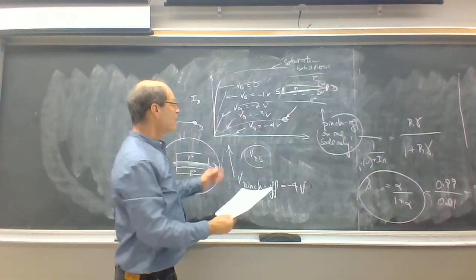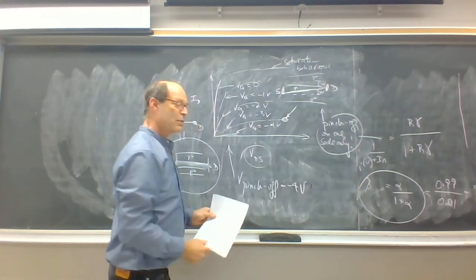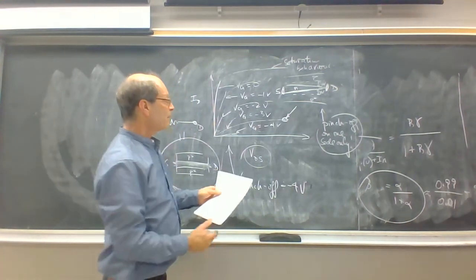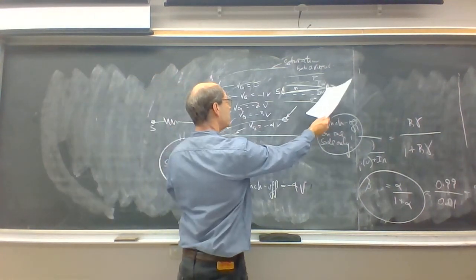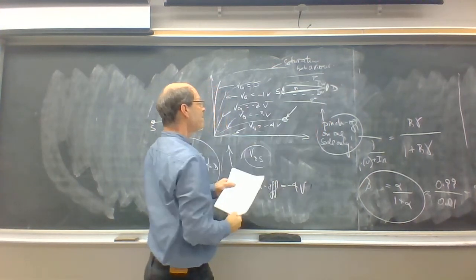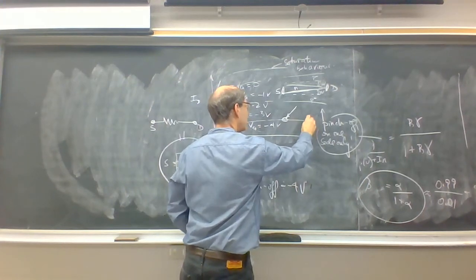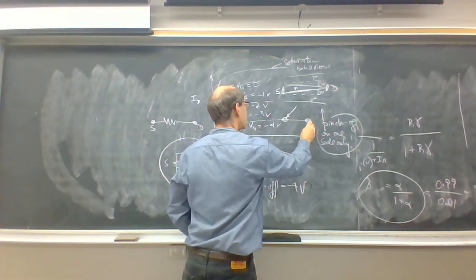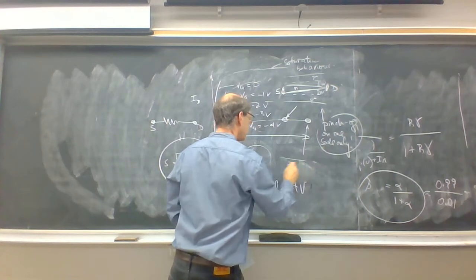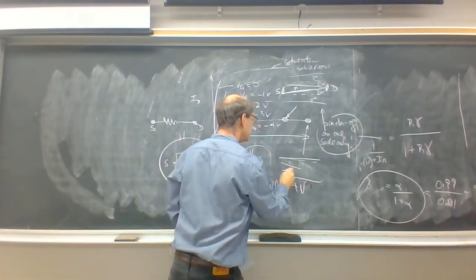What happens is you can change the voltage across the drain and the source, and you'll move the pinch-off point inwards towards the source. So if I go to a higher operating point like that, the device would look more like this.